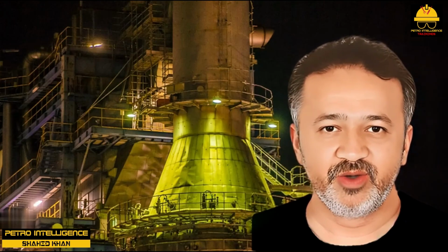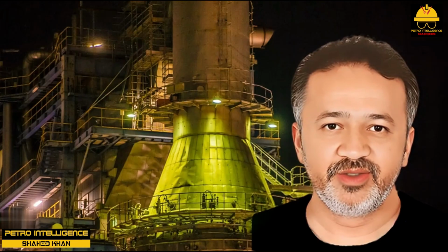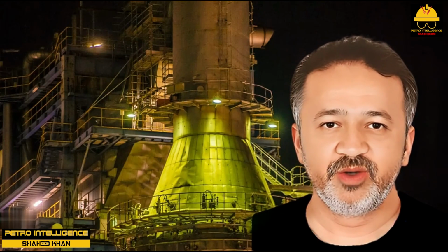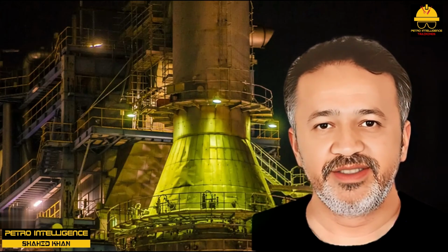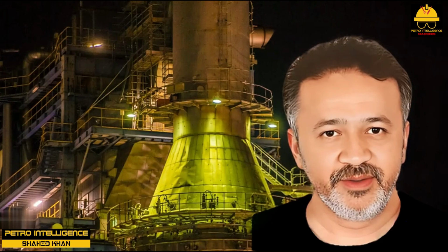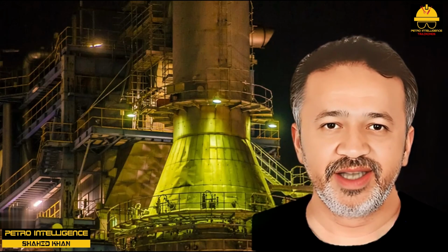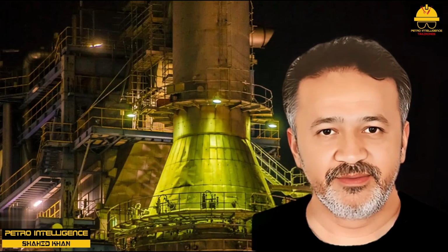The comparable values for hydrogen are 4%, too lean, and 75%, too rich. This suggests that refinery fuel gas, which may contain 5 to 50% hydrogen, can explode much more readily than natural gas. The presence of H2 in fuel gas is a strong argument, then, for connecting pilot lights to natural gas, which is very low in H2.